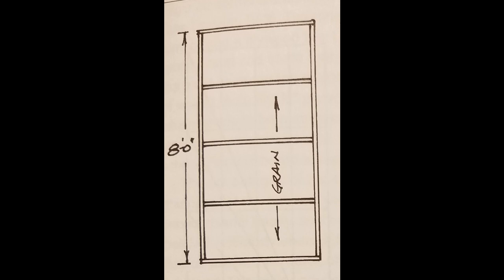Now, typically in construction, or at least in theater, all of our toggles are usually about 2 foot offset from each other, and that gives you a pretty good dispersion of weight. We aren't as strict as commercial construction because we have the ability to claim all of our structures as temporary versus permanent structures. If all of our things that we built were meant to be permanent installations to the building, they would follow a much more rigid construction style.